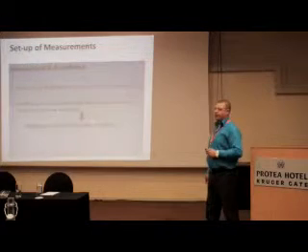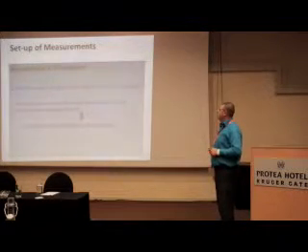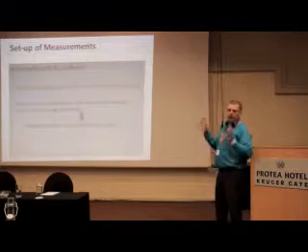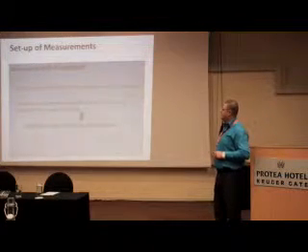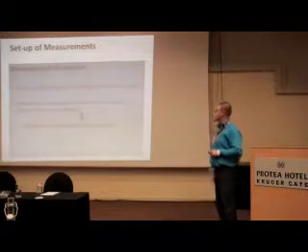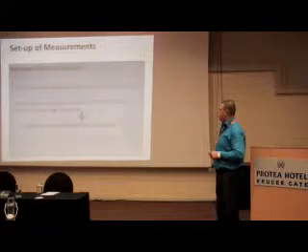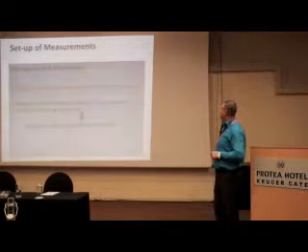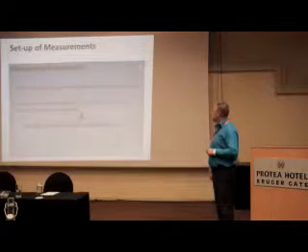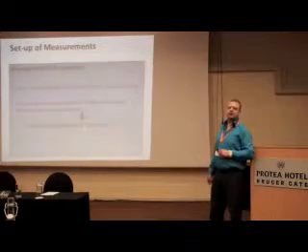For narrowband and broadband, the CFL or other light sources are supplied with 220 volts through a transformer and a LISN. LISN stands for Line Impedance Stabilization Network.